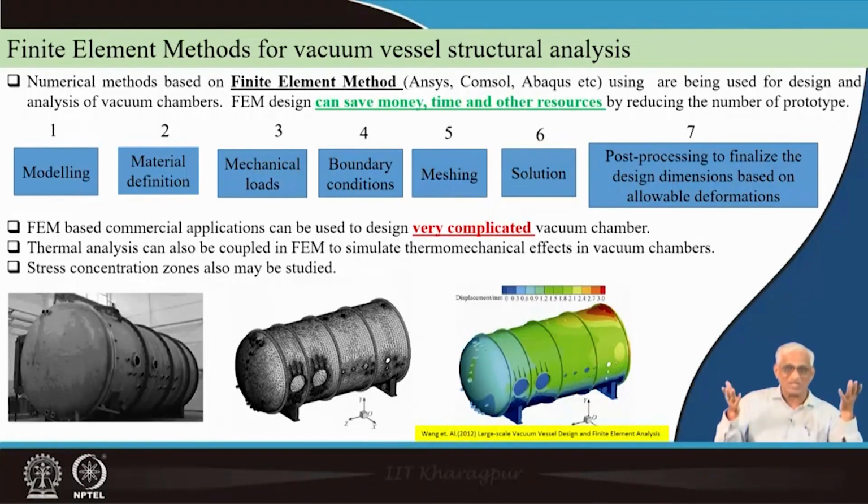Nowadays, we don't have to explain this to engineering students because it is a magic box. The powerful software will take care. All that we need to do is we have to mesh the surfaces. That is where the beauty lies, how best you can do. And in very complicated areas, there are crucial areas, you have to decrease the mesh size so that accuracy of your calculation will be more and more.